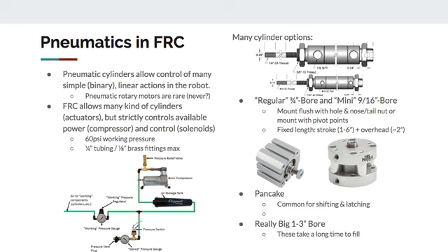So the reason this matters is, I will admit to having failed people in inspection because they have the wrong PSI in their system, and that can hurt you for a day. I've seen it derail teams: everything's fine, and then they can't fix their pneumatic system. If you design for a higher working pressure, or even if you tested it at a higher working pressure, you could be in trouble.